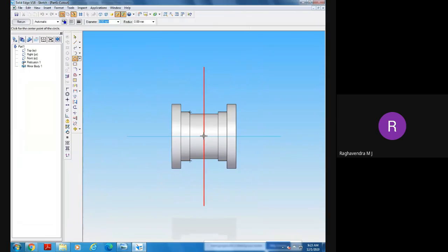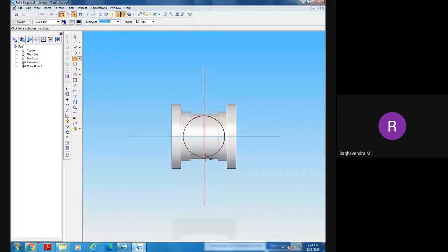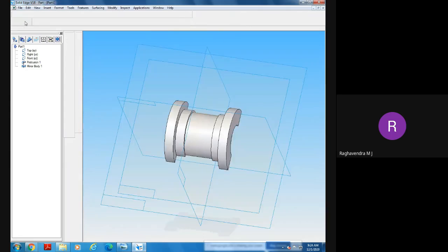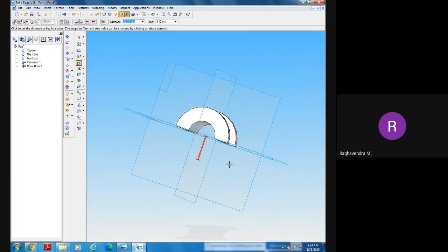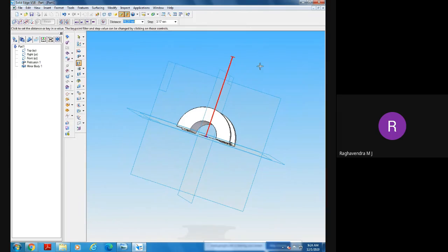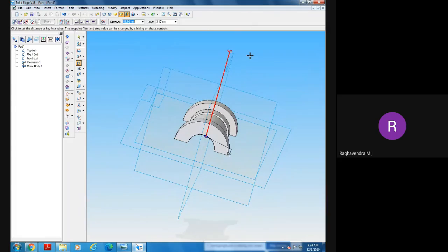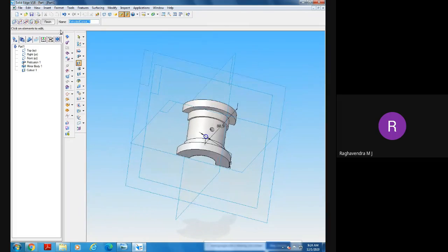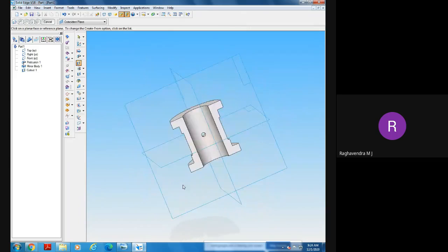Now you select the center. So the diameter is how much? Diameter is 4 millimeters. Go to revolve option. Okay, now which side we have on the plane we have selected this sketch. We have this side material, not this side. So now select this side, drag it, and create a hole. Finish it. Are you able to see that hole?